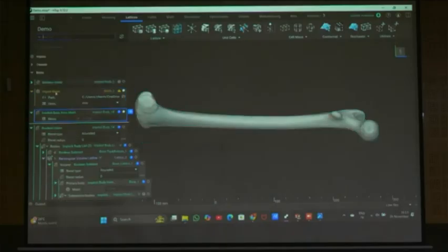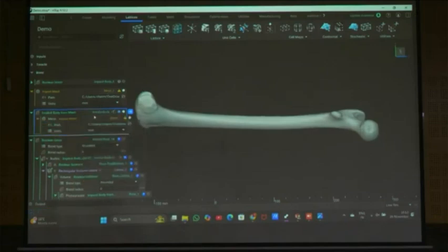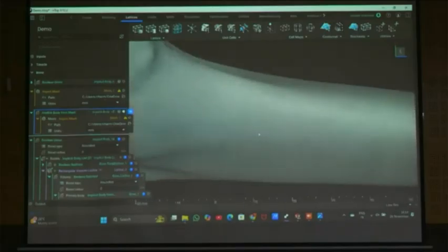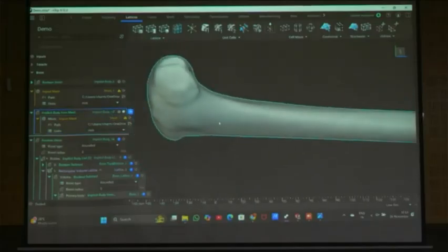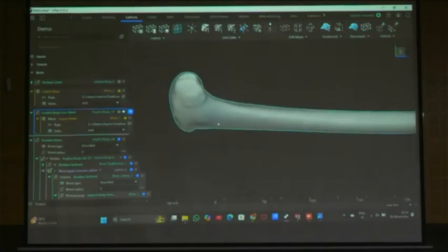I will import this one, I will drag this one. You can see here, as I told you, there is a globe symbol here, and here also a globe symbol. So this will accept. Or otherwise, double click on it and the available options will show. Mesh_1 is the name. You can get this one. See, it converted into an implicit body. Previously our body was like this, now our body is like this. So now we can do whatever operations we want.